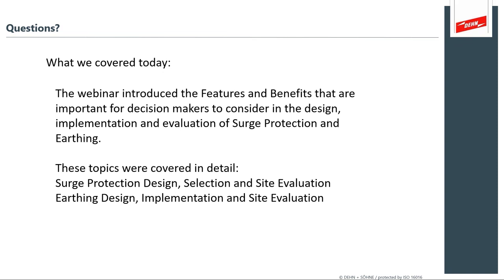DEHN SPDs offer excellent diagnostic features on the AC power and data products. What is generally expected is after severe lightning storms, you want to go through your plant and evaluate if your surge protectors have experienced damage. Basically, the DEHN products are designed to release themselves after they've experienced failure, so that they don't sit on the AC power. So after a heavy lightning event, you will want to evaluate your SPDs.